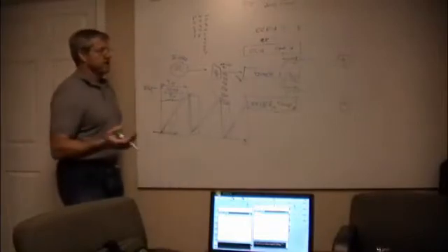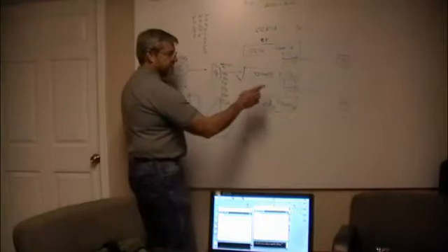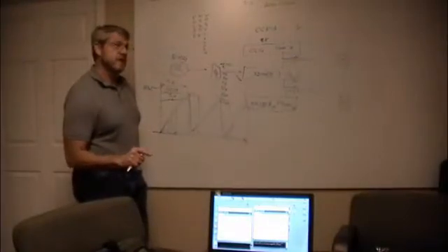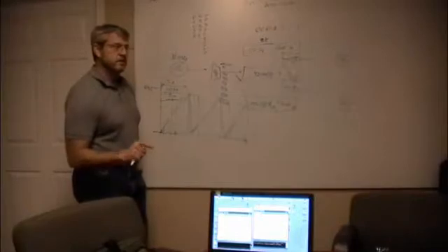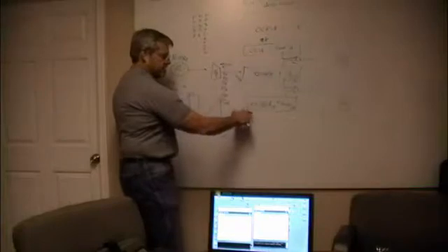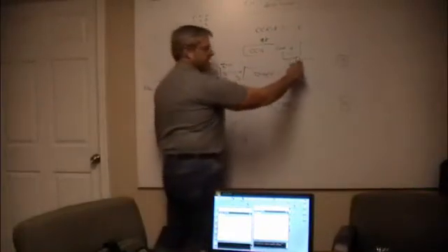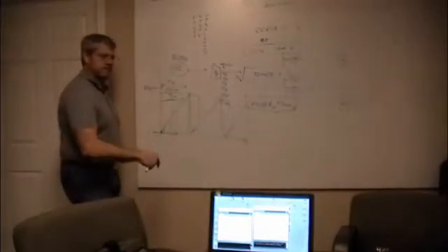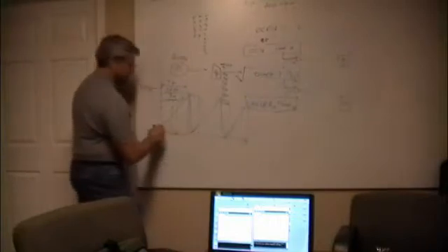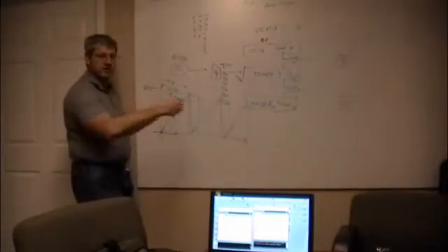Now you can also play a game. I'm going to say this, I'm not absolutely sure it's right. You can do this on OCXA, but not on OCXB. If the count is the same, reset it. So now by changing this value, you can change the duty cycle. Or not the duty cycle, I'm sorry, the period.